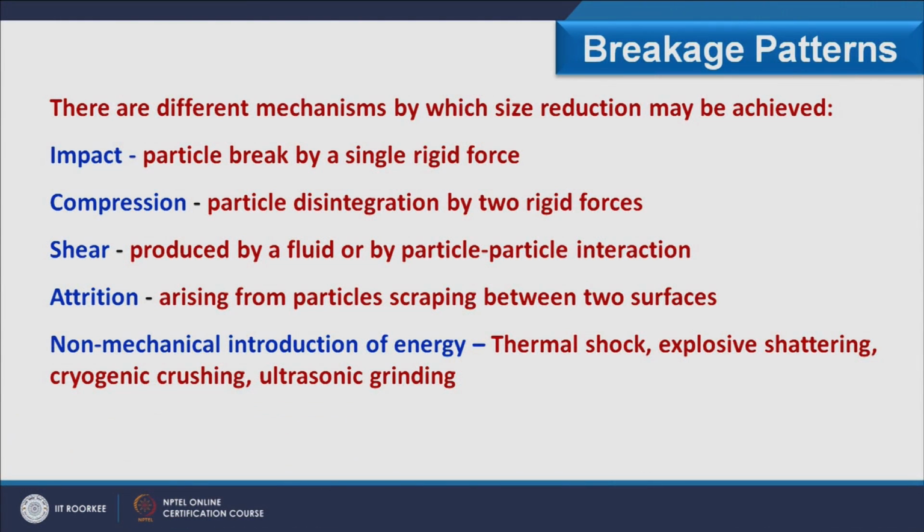After these four patterns, we have another pattern which we call non-mechanical introduction of energy, and this includes thermal shock, explosive shattering, cryogenic crushing and ultrasonic grinding. So, all these five patterns we have for size reduction. In this, the top four are basically used for grinding equipment, and we also have non-mechanical introduction of energy, which we also use for size reduction.